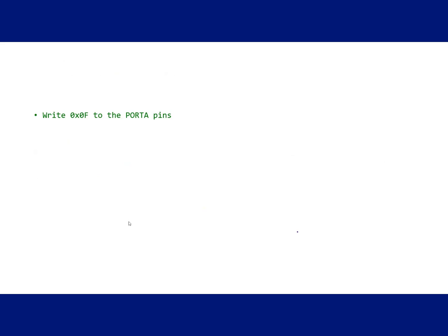Now let's understand one more example. Write 0x0F to the port A pins. In this example, we want to write data to the port pins. Port A contains 8 pins, PA0 to PA7. Now we want to write 0x0F to these port A pins.